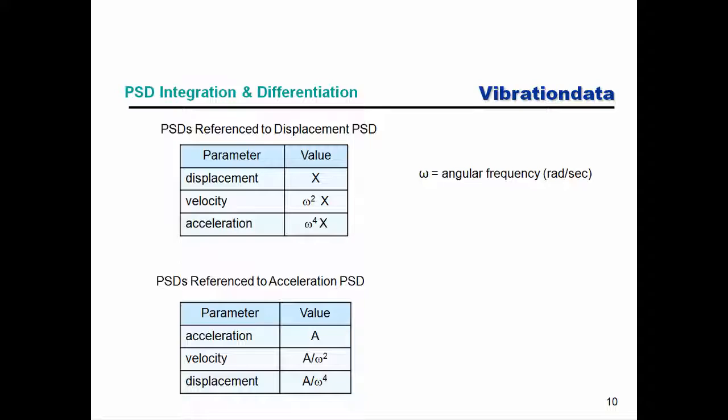And just also to remember, by way of analogy, anytime we are doing an integration, it's kind of like a low-pass filtering operation. So just in your mind's eye, think about as we get to lower and lower frequencies, that velocity PSD is really going to jump up in terms of its amplitude at lower frequencies, and even more so for the displacement PSD.